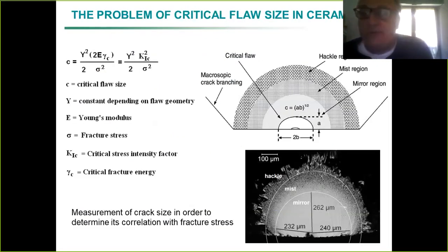So ceramics, what you might have realized is that ceramics break in strange ways, which are not the typical ways of metals, and which are quite repeatable. Well, you have a ductile, a brittle fracture. Here you can have complex ways of breaking, which are connected. In particular, they tend to be brittle, and they are connected with the dimension of the crack. This is of the flaw, if you want, the defect.